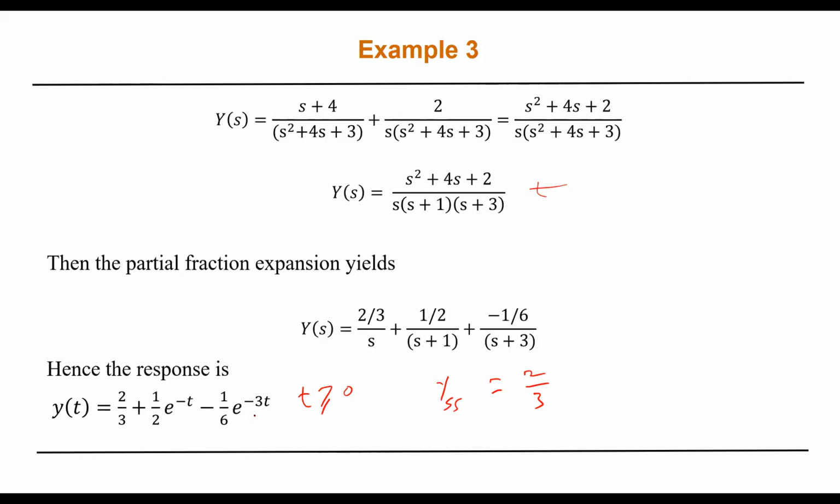But okay, we are using steady state where the time goes to infinity. As I said, I can get the same result by applying the final value theorem. That's basically y steady state equals the limit as s goes to 0 of s Y(s). This is the same as y steady state, which is the limit as t goes to infinity of y(t). Okay, so they are the same.